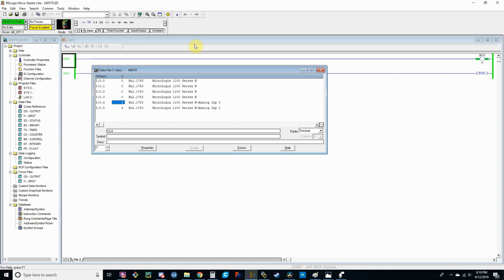Anyways, as I turn my sensor up and apply more voltage to it, you can see my values are increasing. It'll go up, up, up. And normally, if I applied 10 volts to it, it would go all the way up to 1023. This little voltage simulator that I made, for some reason, when I hook it up to the PLC, it's only outputting about 9.4 volts. So that's why when I turn my simulator up all the way, we're only seeing 1003, 1004. So don't let that confuse you. That's just something on my end that happens.